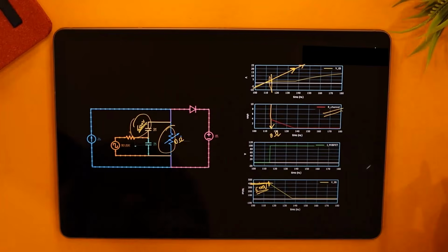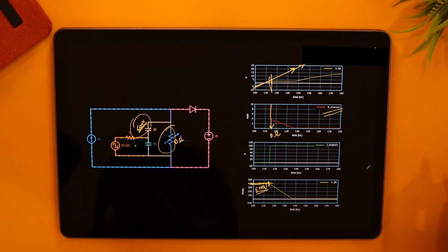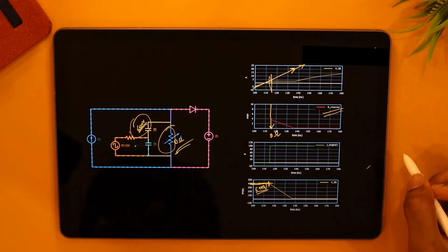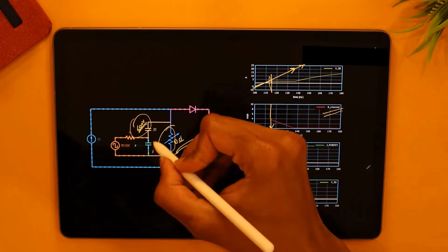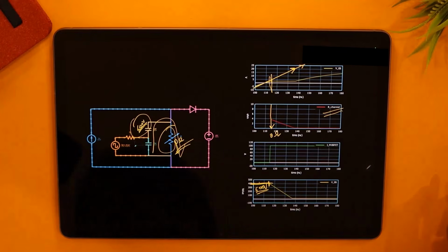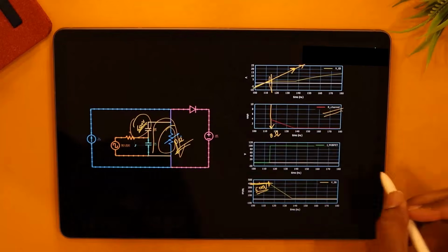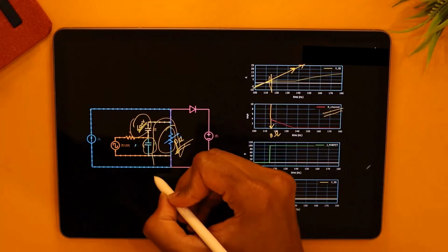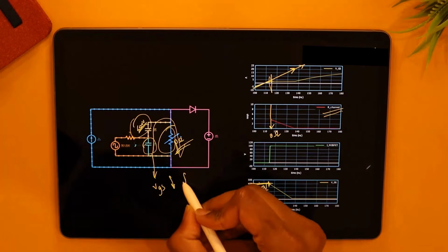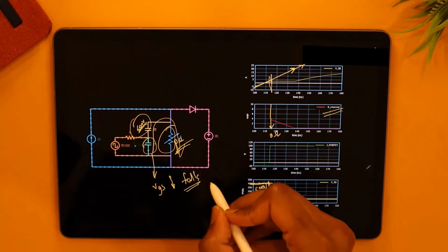Now 400 volts of CGD and CGS charged together, they are seeing a short circuit of 0 ohms across themselves. What would happen? They would instantaneously discharge into it because it's like a perfect short circuit. And if they discharge into it, what will happen to the voltage across the CGS, which is essentially VGS? It will fall.